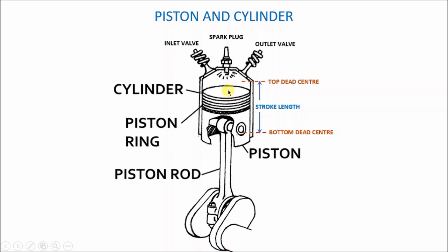And when it reaches that position, immediately the spark will ignite, the spark plug will release a spark, okay? That is why it's called the spark plug, because it releases a spark. And because already the mixture inside of the cylinder was already at a high temperature and a high pressure, that little spark that the spark plug is going to release is going to cause a sort of explosion inside of the cylinder. And when that explosion takes place, that will cause the piston to move down.